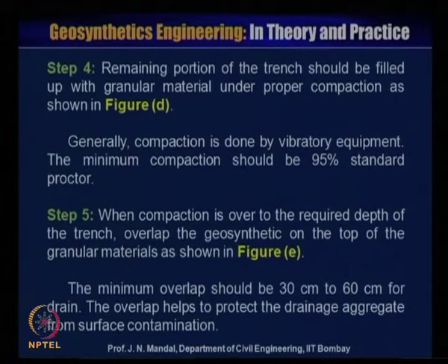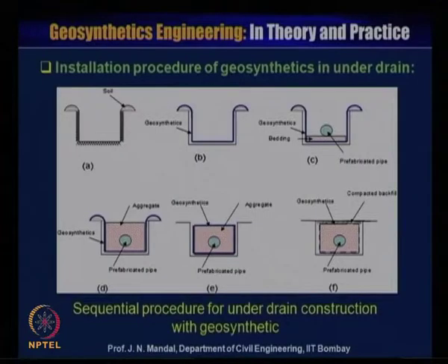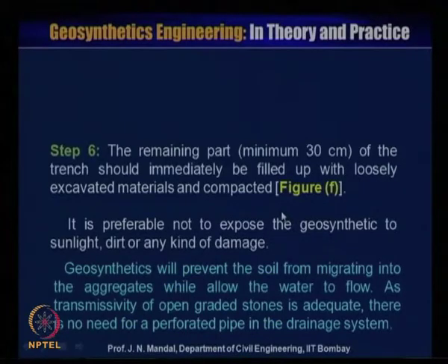The overlap helps to protect the drainage aggregate from surface contamination. You can see here the geosynthetic material is wrapped on the top.